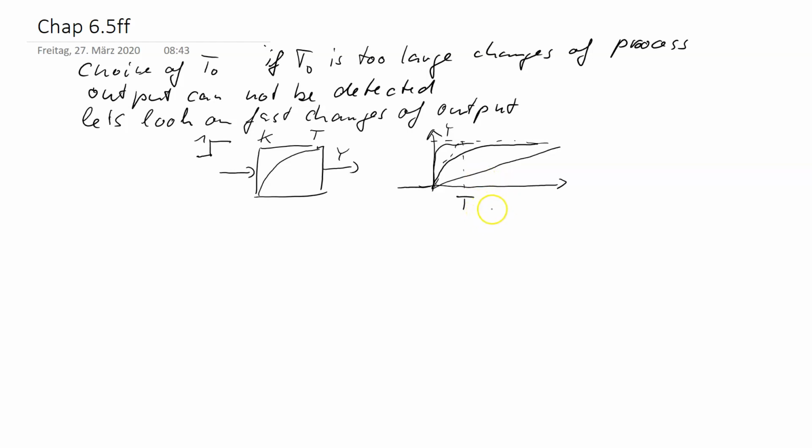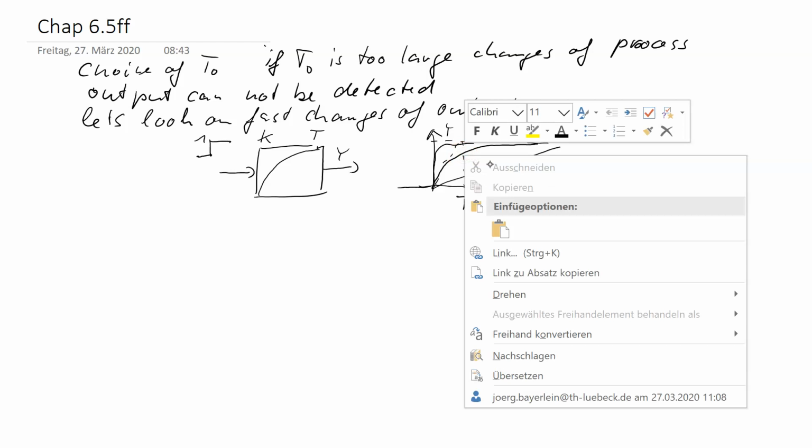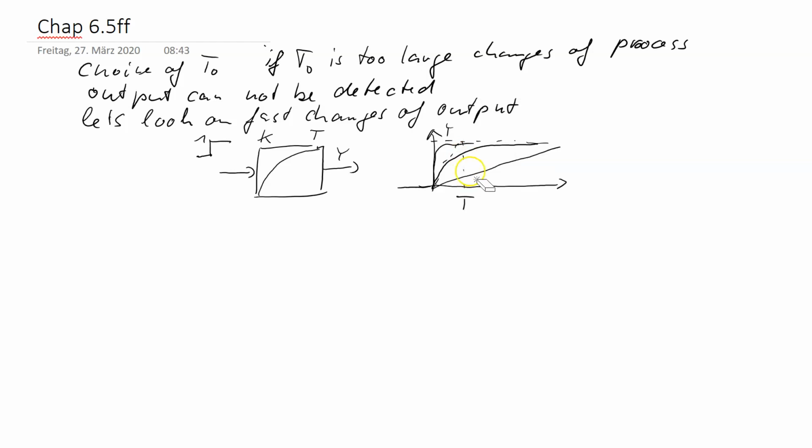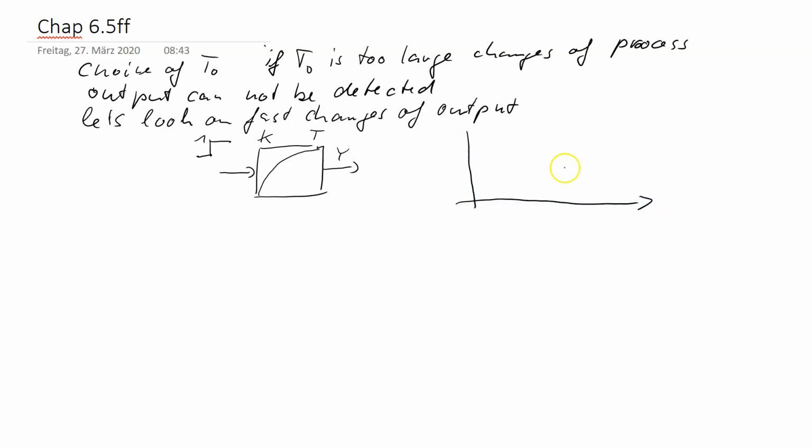And that is what I want to show you. I wiped it out and redraw it with one curve after one time constant. In the typical exponential function output of my PT1 system, if this is k, the point at one process time constant is 63% of k.